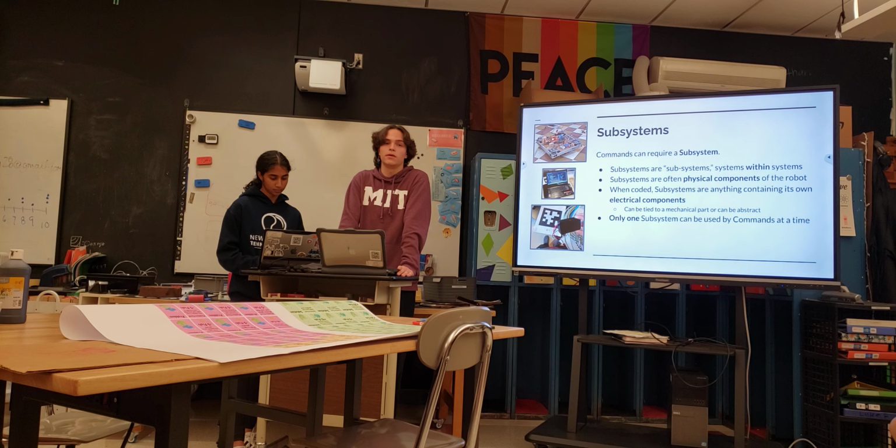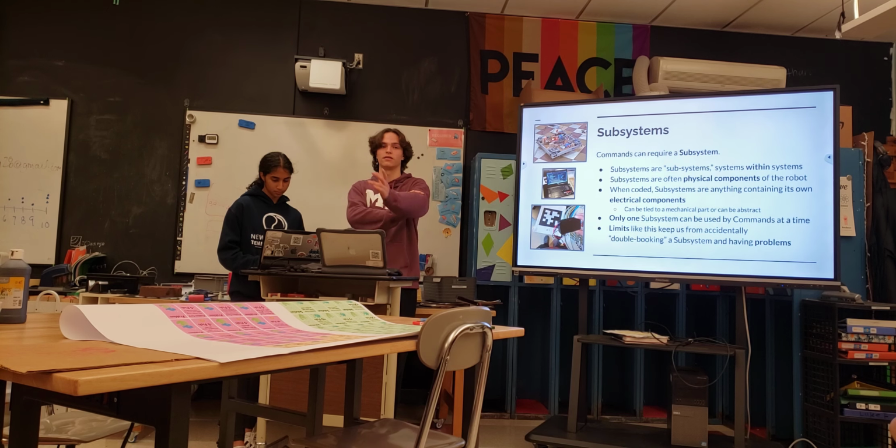Only one command can use a subsystem at a time, and these restrictions keep us from breaking the robot. If we had two commands trying to move an arm in opposite directions, the motor would go haywire.